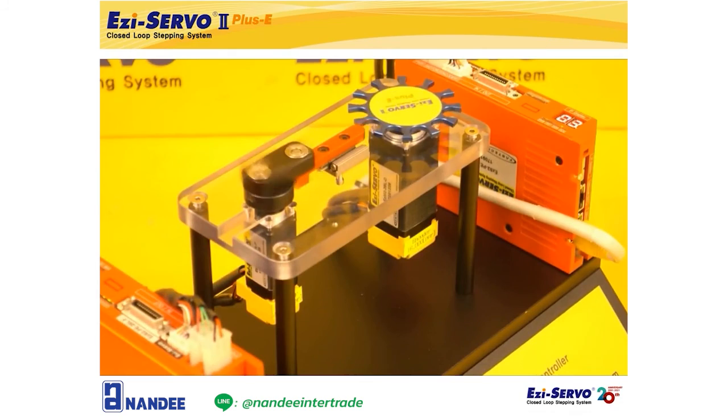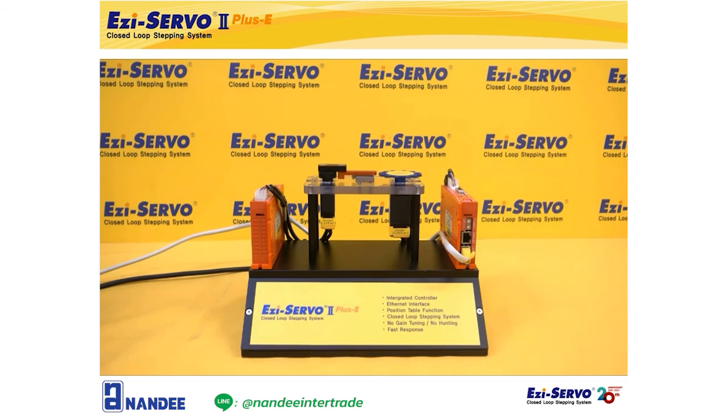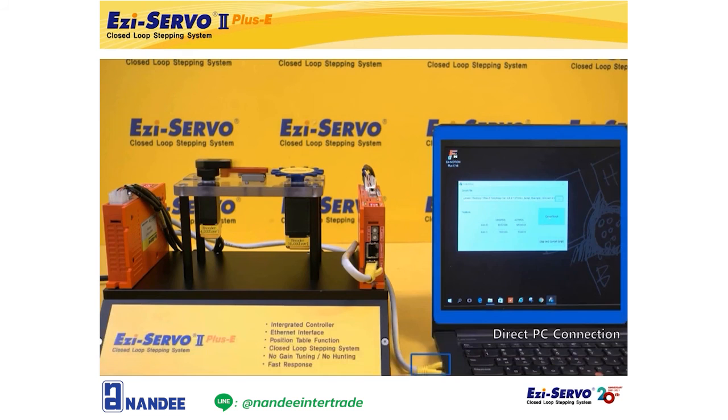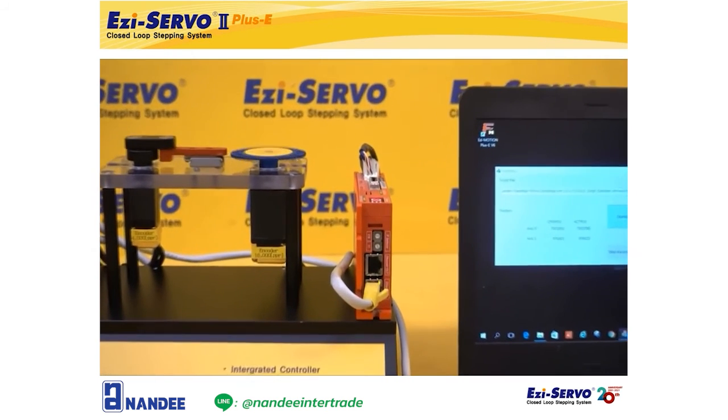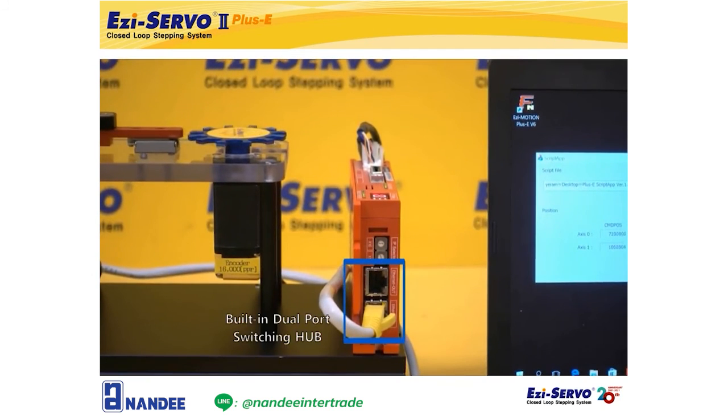Because it is a closed-loop stepping system, precise position control is possible through a high-resolution encoder, and it is optimal for such high-speed, short-pitch motion because of the characteristic of a stepping motor without hunting after stopping. In addition, by directly connecting Easy Servo 2+E to a PC through the Ethernet port, it is possible to simply control it with the API provided by FASTECH.